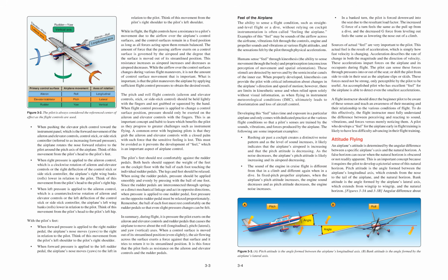The pilot's feet should rest comfortably against the rudder pedals. Both heels should support the weight of the feet on the cockpit floor, with the ball of each foot touching the individual rudder pedals. The legs and feet should be relaxed. When using the rudder pedals, pressure should be applied smoothly and evenly by pressing with the ball of one foot. Since the rudder pedals are interconnected through springs or direct mechanical linkage and act in opposite directions, when pressure is applied to one rudder pedal, foot pressure on the opposite rudder pedal must be relaxed proportionately. Remember, the ball of each foot must rest comfortably on the rudder pedals so that even slight pressure changes can be felt.